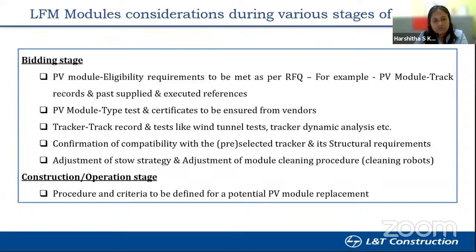Similarly, the compatibility of these modules with the tracker, I'm sure the next panelist will be explaining more on this. It is very important that, if we are doing tracker-based projects, the tracker is capable of handling these large format modules, with respect to specific tests, whether they have been conducted in terms of internal tests and tracker dynamic analysis tests, etc. So the compatibility of the selected tracker with the modules and its structural requirements need to be checked.